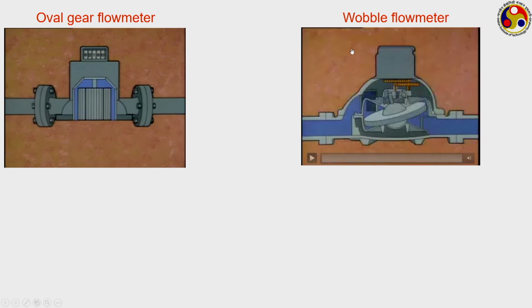The oval flow meter is actually more common in fuel stations, the gasoline stations. You can see this kind of flow meter commonly. Here, instead of any gears, you have a large plate, just like shown here. This plate is mounted on the base on a kind of hinge, such that it is able to oscillate in its own position depending upon the direction of the flow.